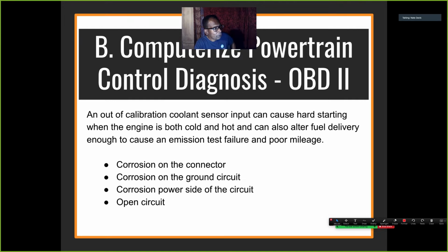Yeah, so remember, on the coolant sensor, the PCM is measuring resistance, a voltage drop off resistance. And remember this also: anytime the computer is measuring a sensor input, it's doing a voltage drop off that sensor. In this case it's a coolant sensor. The coolant sensor has two resistors in the circuit. One is fixed, one is a thermistor. A thermistor means it changes resistance with temperature. So if that coolant sensor had additional resistance on it, the computer's not going to know it. It just sees the additional resistance. So when there's a voltage drop across it, it's going to think it's a colder car because of the additional resistance.